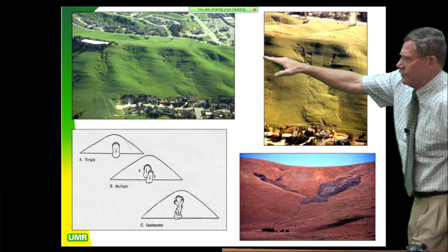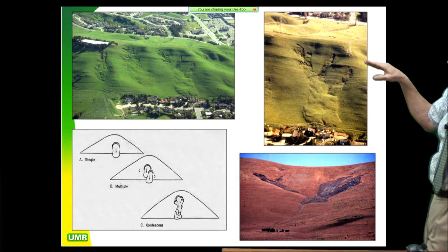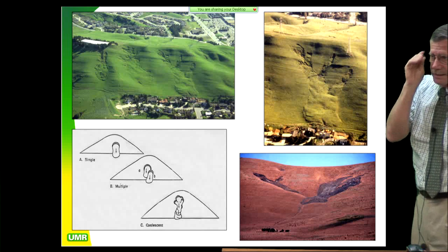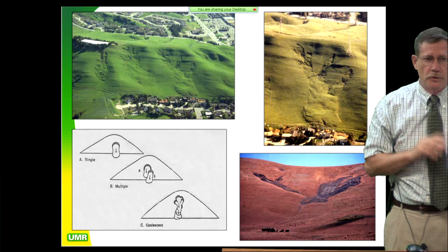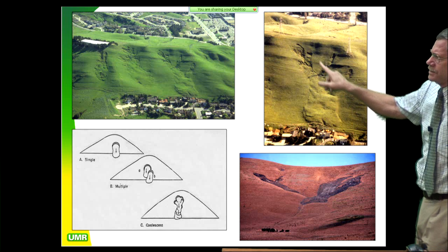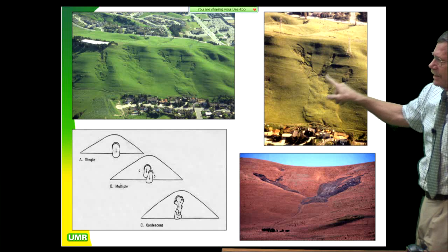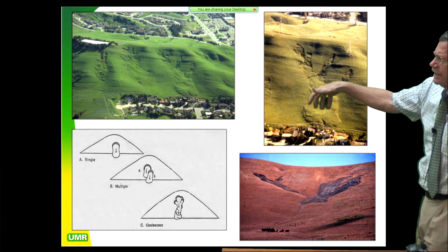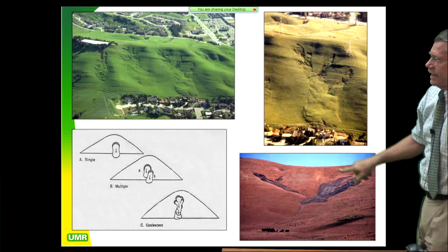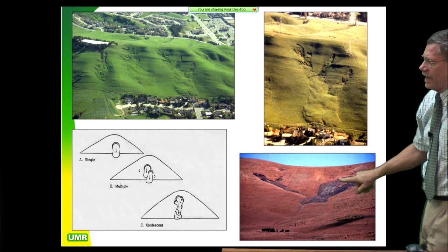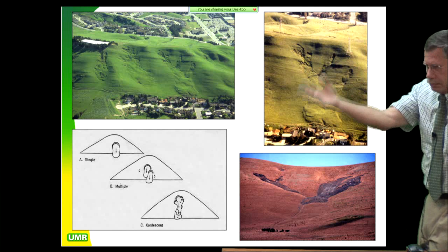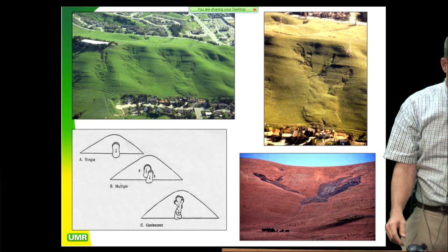These are conglomerate lenses. These little hard things running through here are conglomerate lenses. Conglomerate lenses are like water trucks delivering pore pressure to you. No charge. They just deliver. And so you have very high pore pressures, and you have high drop here, so you get high head feeding into this thing, and this water feeds down in here and it can't get out of the clay. So that's how come you're getting this kind of vomiting on the hillside like we looked at last week. It's just flowing around.